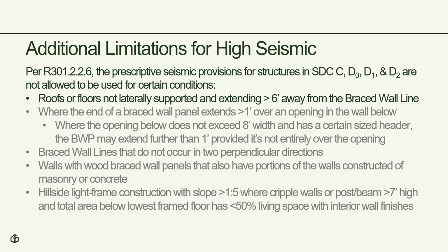Now that we move into the actual application of how those loads will transfer through the building, I want to recognize that there are additional limitations in the IRC for buildings in high seismic design categories. The first limitation is where you have roofs or floors that are not laterally supported and that extend greater than 6 feet away from a braced wall line.